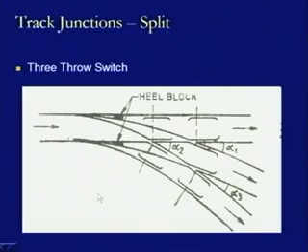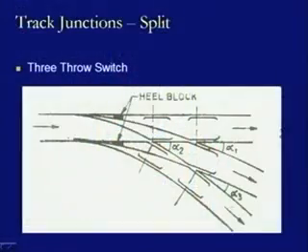Then in this case, this was the contrary flexure condition. Now, this is a similar flexure condition where the 2 tracks which are coming out of the main track are moving in the same direction, not opposite to each other. And the only difference in this case is that one track is having more flexure as compared to the other turnout track, and this other turnout track is having more flexure as compared to this one, which has a straight profile, that is the main track.